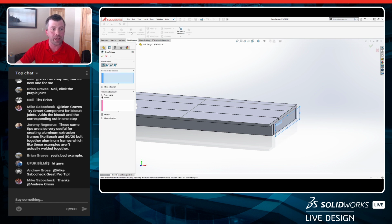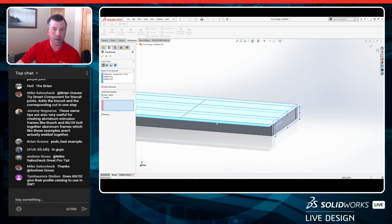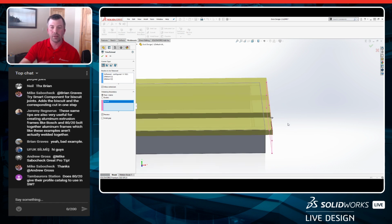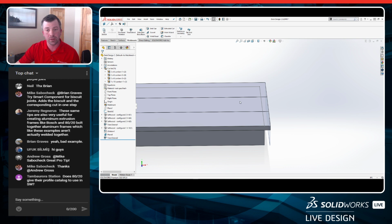And I can use the trim extend. I could do it before I did the pattern, or in this case, we'll do it to all these bodies. And we're going to say a face or plane to extend to. Bam, just like that. Just going to extend those out, update the cut list to the appropriate size, and then we'll remember that we wanted 120 inches, so it's probably not a good idea, and I ended up not doing that, but for the sake of the video, we're live. Let's go ahead and just extend that out, and that's how easy it is to modify from an existing sketch. Trim, extend, super powerful tool inside of Weldments.